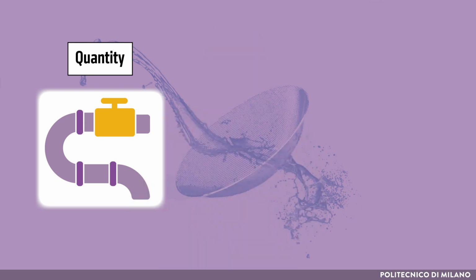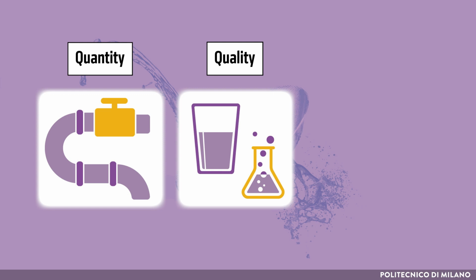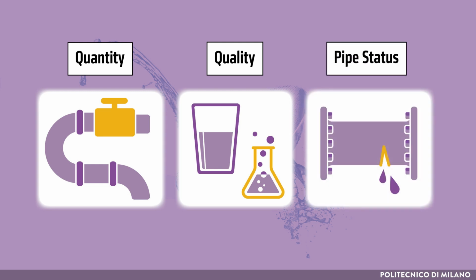The second one includes sensors to monitor water quality by means of chemophysical parameters such as temperature, ionic conductivity, that is salinity, pH, and concentration of specific ions or molecules or even biological entities. And finally, sensors to monitor the infrastructure which transports water, typically pipelines made of metal or plastic that can be affected by fouling, corrosion, and leakage.